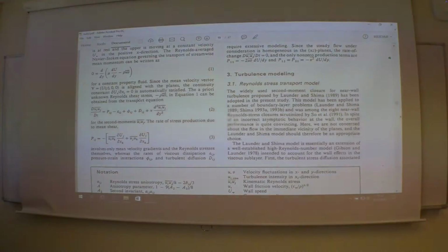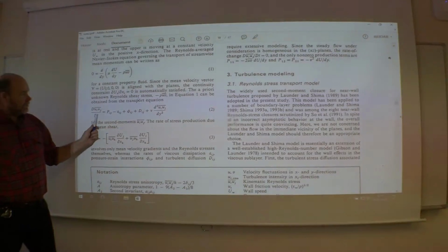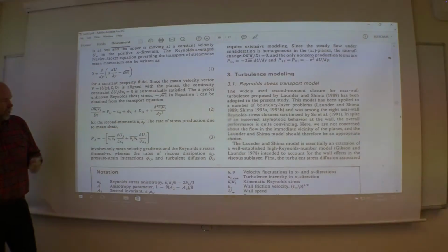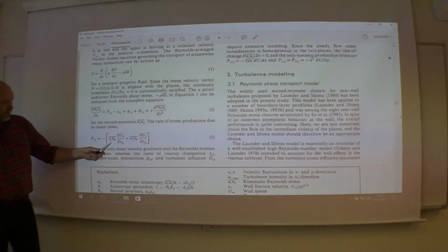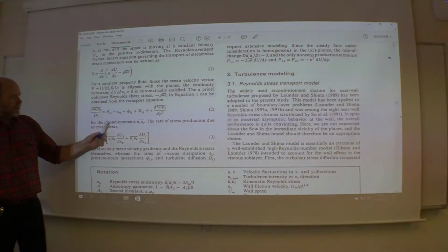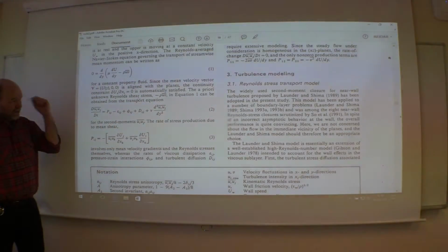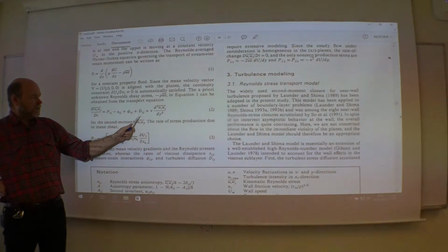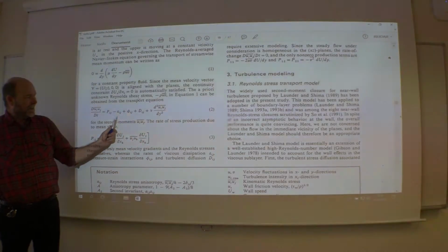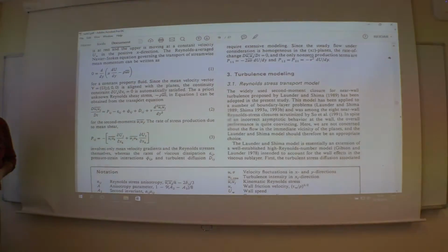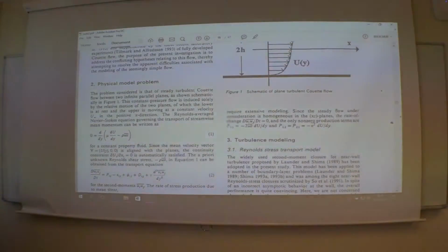So here they have done a full Reynolds stress model. Everything as normal. Production term is analytically correct. You don't need to model that one. You need the dissipation. Here redistribution and diffusion. And here they have another dissipation term as well. Why they have kept that one alone? Well, people tend to play around with the different terms in the diffusion terms. Some you might call this one a dissipation since it has viscosity in front, but that's your choice.